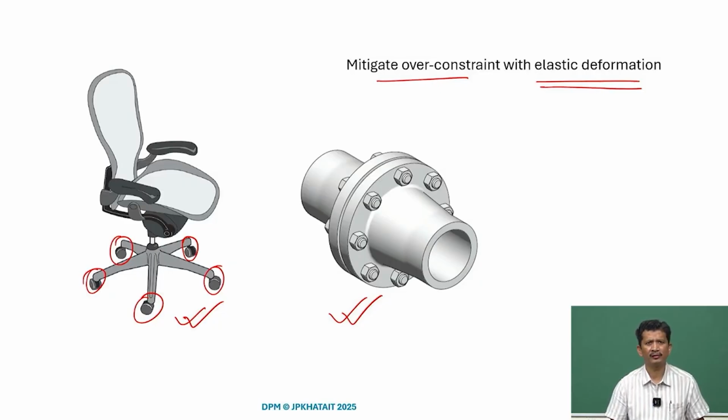Therefore, it is not desired, and we will see some examples where the location and the clamping can be achieved using exact constraint design. We may not have to worry about the proper alignment, it will go to the same location all the time. If we create some features on the surfaces, then we can bolt it and secure the joints.